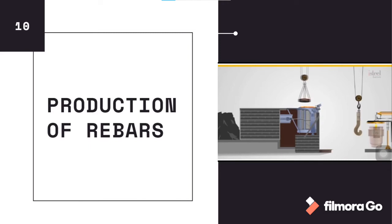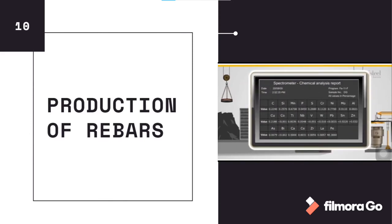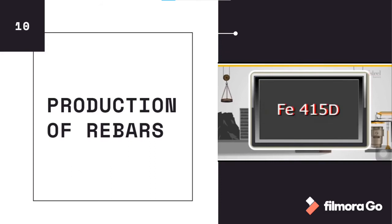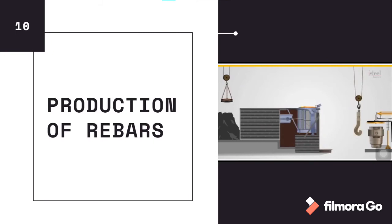During steel making, at regular intervals, the liquid metal is tested to ensure that the chemical composition is as per ISI specifications. The chemical composition must be right to get the right properties and various grades of steel, such as Fe415, Fe500, Fe550, and CRS, that's corrosion-resistant steel. Carbon gives strength and manganese provides flexibility.